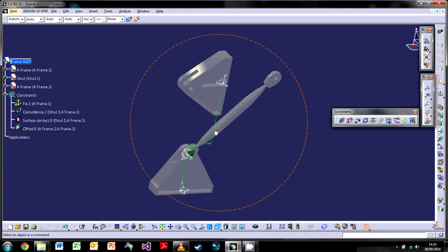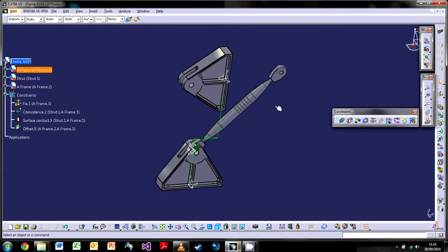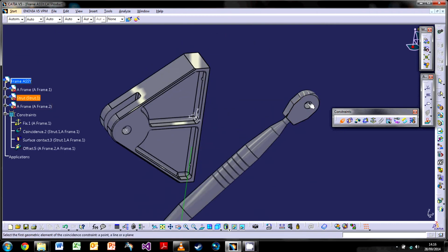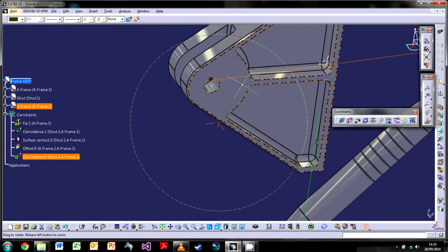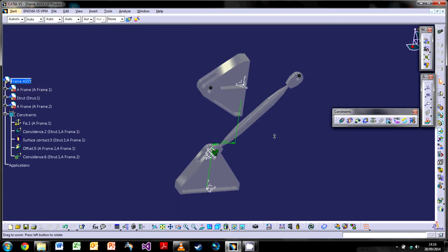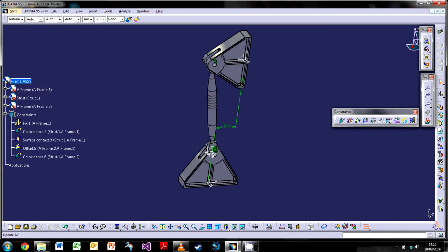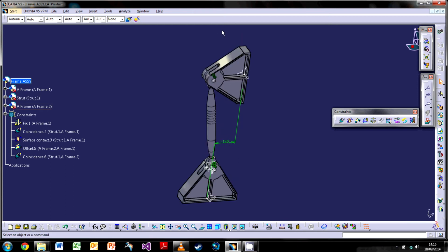So if I was to define that as an offset, and then go to constraint, and because I'm defining this afterwards, the constraint is going to basically be a slave to the offset. So update it, and you'll see that's moved up in order to satisfy this length here.